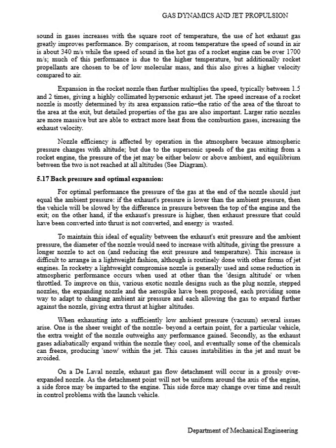When exhausting into sufficiently low ambient pressure, several issues arise. Firstly, the sheer weight of the nozzle: beyond a certain point for a particular vehicle, the extra weight of the nozzle outweighs any performance gain.